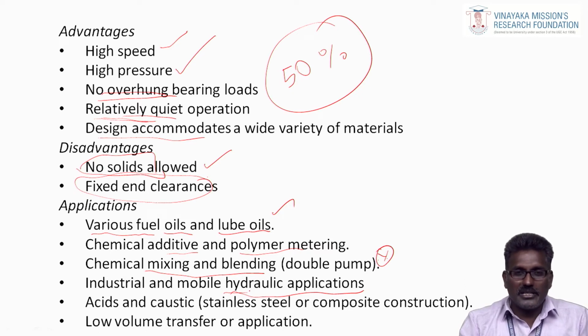For example, the engine generator is 3000 horsepower, and the road wheels number 6 for most diesel train engines, each wheel having 500 horsepower. So that 3000 horsepower is shared by these 6 traction motors, each designed for 500.